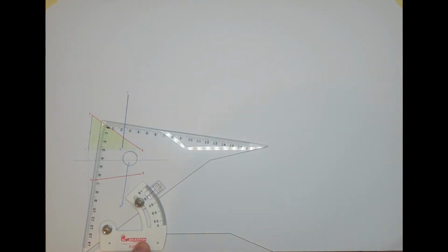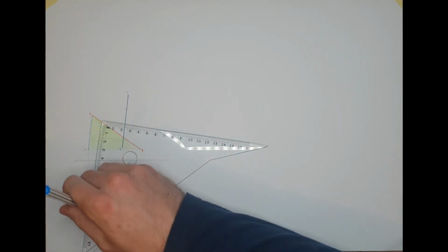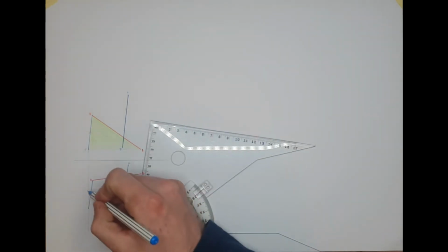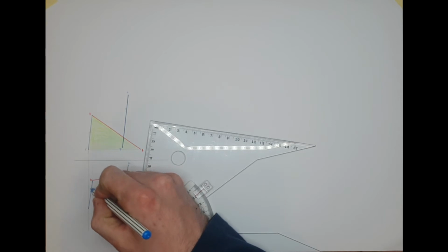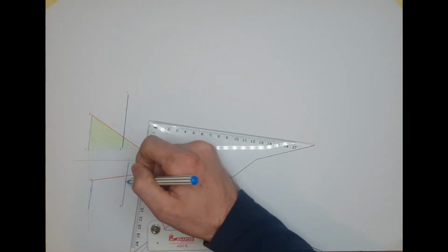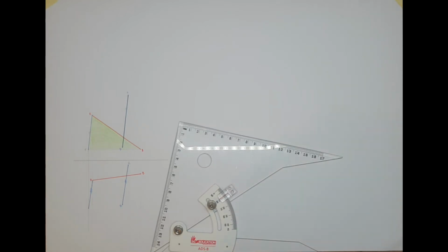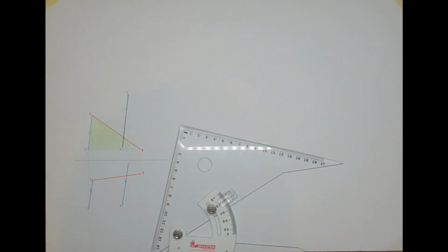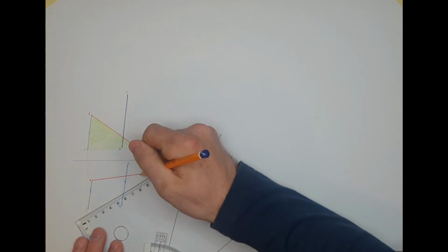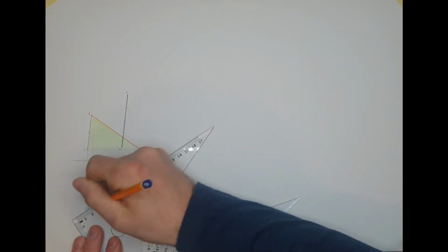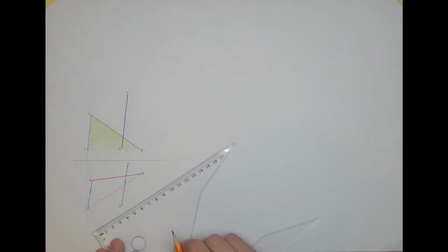And that parallel, 3 strikes through this time, to the line CD from A, and that gives me the point E right here, and then I'll join E back to B, and there's my green plane in plan.